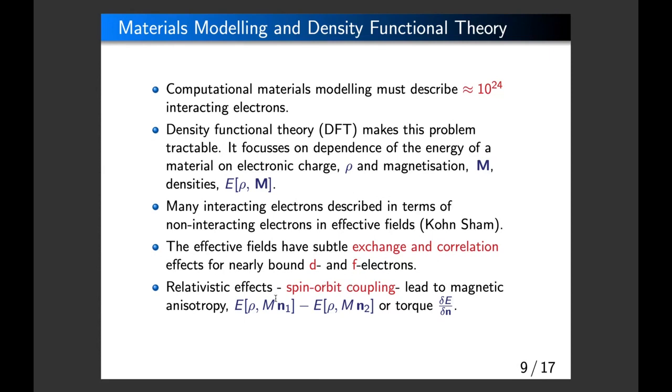In particular, one can evaluate the difference between this energy if it's magnetized along one crystallographic direction, and see how it's different from if it's magnetized along another. And then from that, one can generate the magnetic anisotropy, which you could feed into generating some magnetocrystalline anisotropy coefficient for these longer length scale models of magnetic materials. So that's in a nutshell what lies at the heart of this modelling. Are there any questions about that?